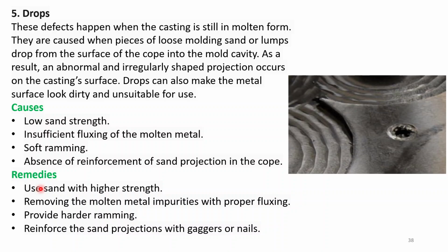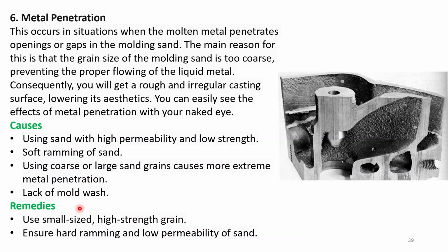Remedies: we can use sand with higher strength, remove the molten metal impurities with proper fluxing, provide harder ramming, and reinforce the sand projections with nails. Next is metal penetration.